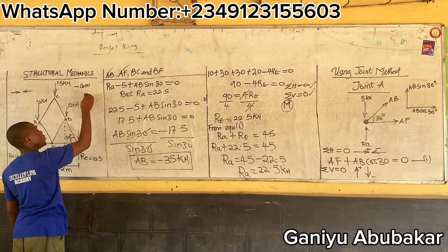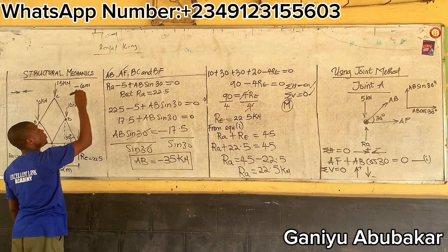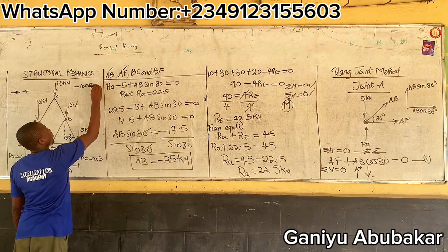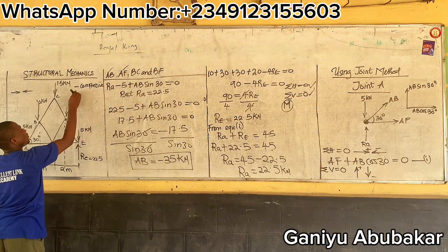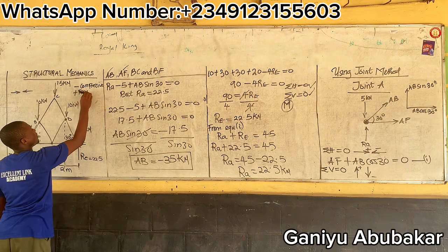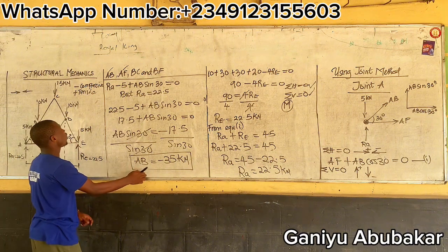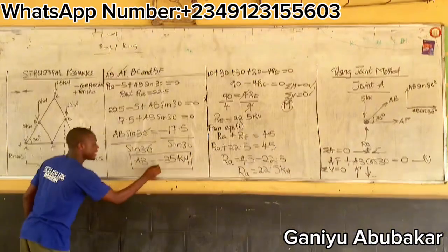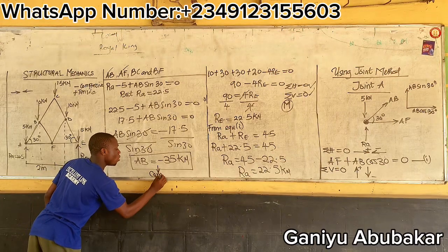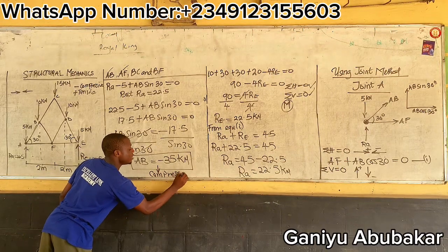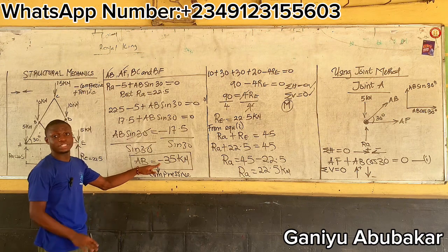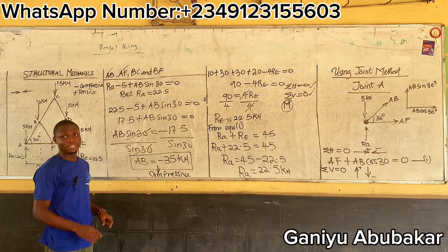A positive answer, you call it tensile. What will I call the negative answer? Compressive. Just know the sign. If it's positive, it's tensile. Negative, compressive. That's the concept.